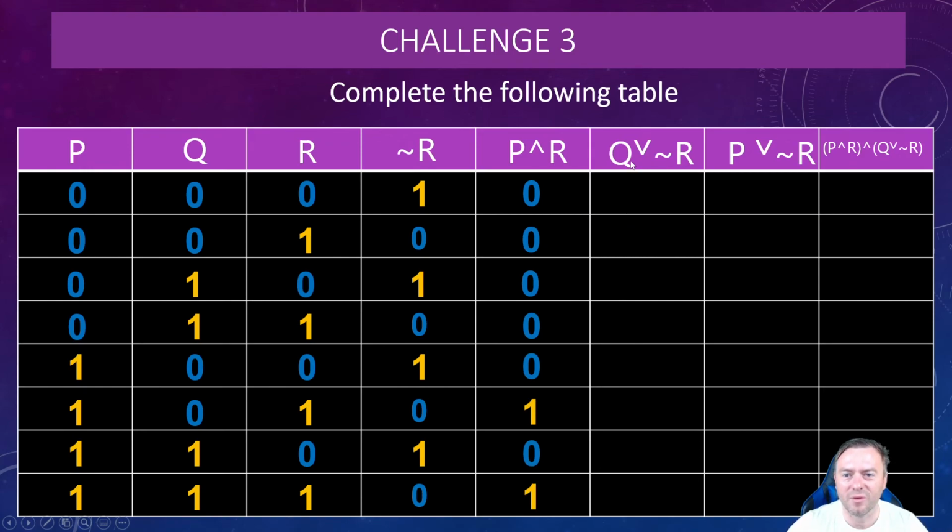The next one, then, we've got Q or not R. So you've got Q and then the not R. All you're looking for is any time there's a 1. In this case, a 0 and a 1 makes a 1, a 0 and a 0 makes a 0, a 1 and a 1 makes a 1, a 1 and a 0 makes a 1, a 0 and a 1 makes a 1, a 0 and a 0 makes a 0, a 1 and a 1 makes a 1, and then a 1 and a 0 makes a 1. So that becomes a little bit broader.